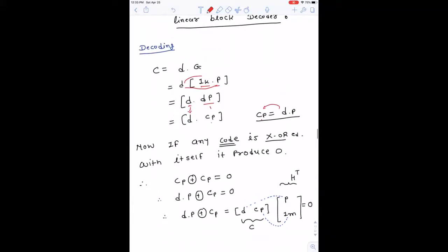Now in the XORing operation, if you understand the XORing operation, you can tell there is an X input and a Y. This is the XOR gate. So in the XORing operation, if in the second input, this is an external input, we have the same value X, then Y is always 0.